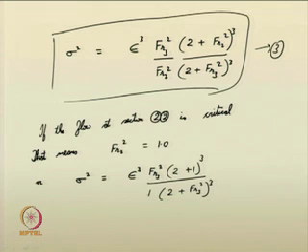But for the flow at the obstruction section to be critical, you require a certain width ratio, that is B2 by B3, the square of that ratio will be obtained based on the downstream Froude number. So, what is that Froude number that gives critical flow at the obstruction site? What is that Froude number? So, let us now suggest that.